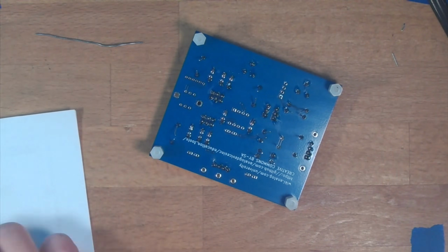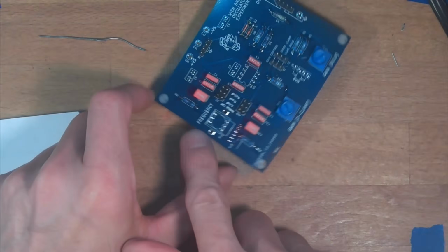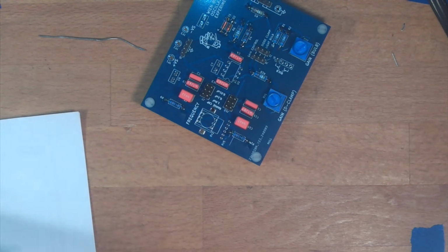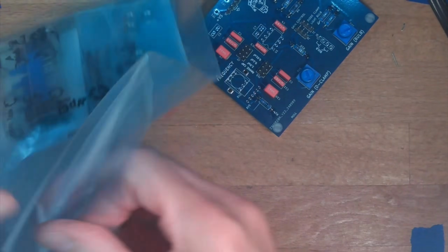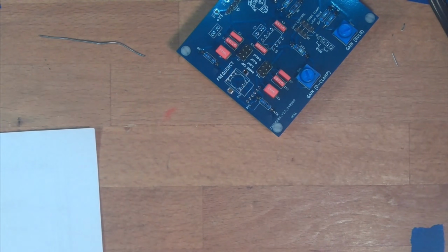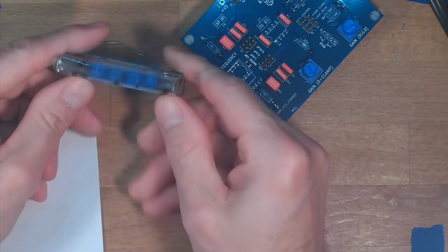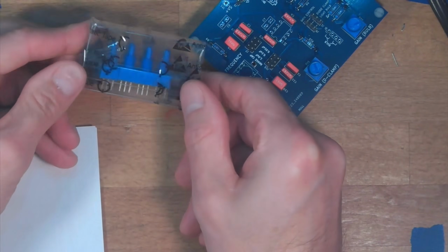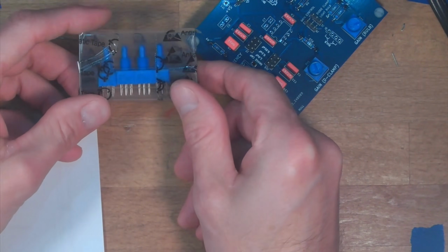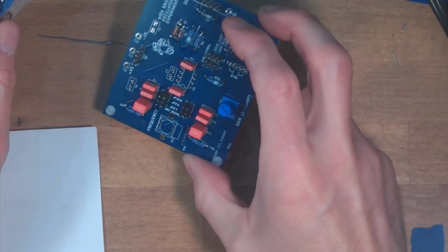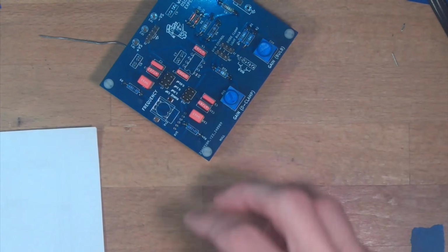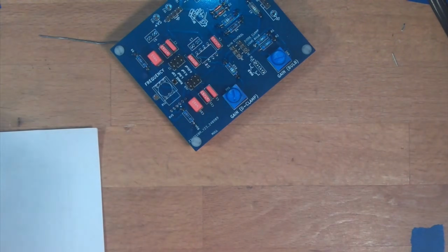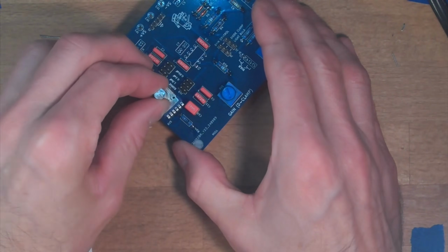All right, and so the footprint for the potentiometer here is kind of nested. And the reason for that is when I first did the prototype here, I was looking through DigiKey and I found these potentiometers, which are really nice. They're kind of cute and compact. They're also $9 a piece, which is fine if you're building one board, but if you're building 10, that starts to eat into your budget. So I nested another footprint for a much cheaper dual 10K potentiometer. So let's install that guy.